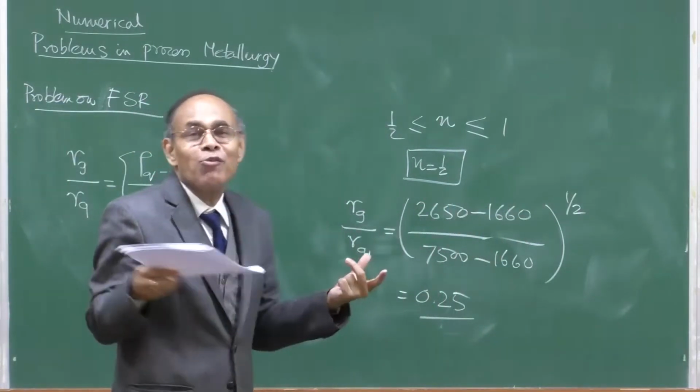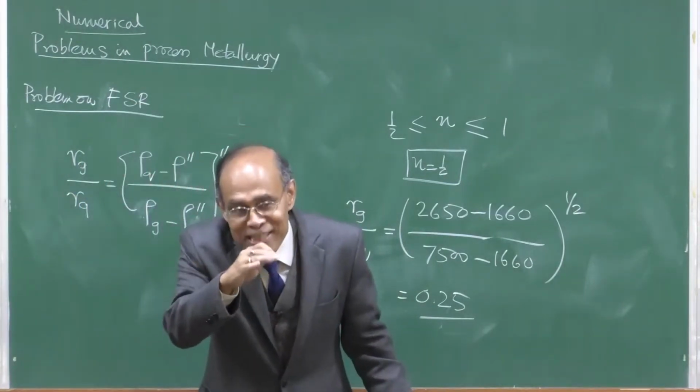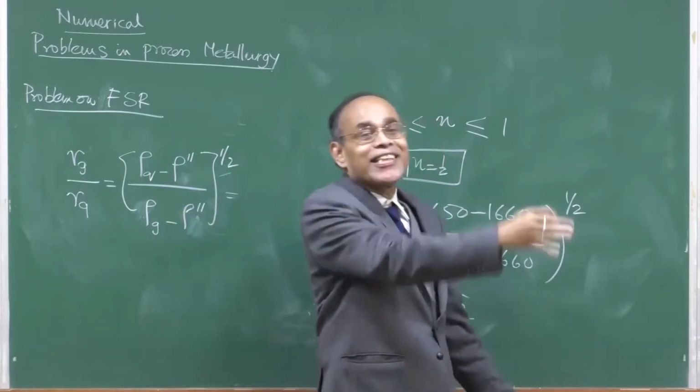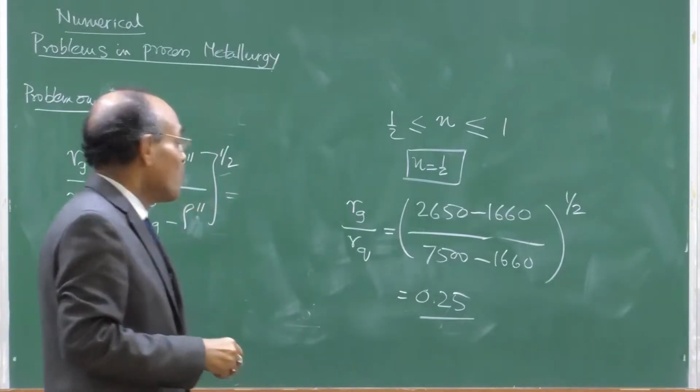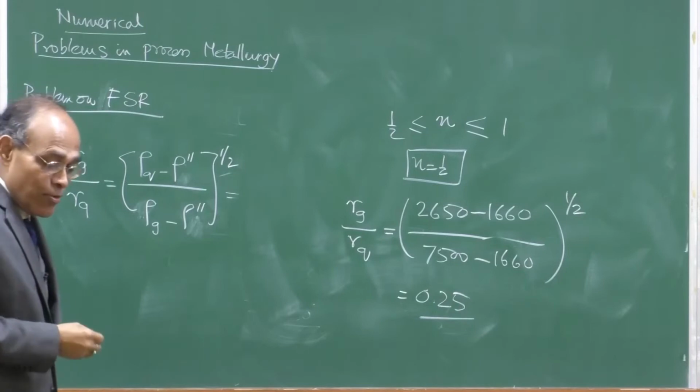So, free settling will rarely be obtained. Whatever values we obtain on the basis of the free settling ratio, we can expect that the actual scenario is going to be better than that, because the lighter particles are going to experience more resistance while they settle to the bottom of the vessel during the classification process.